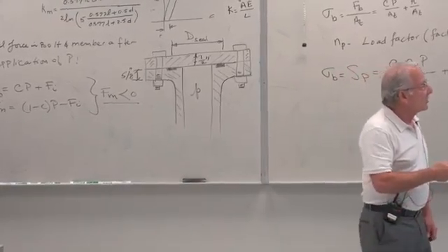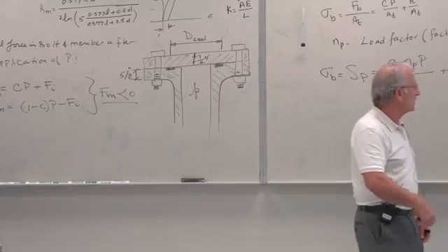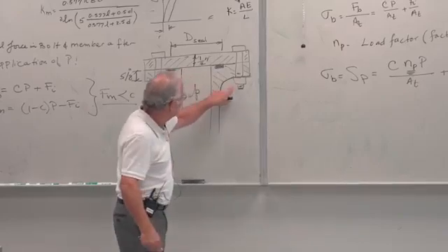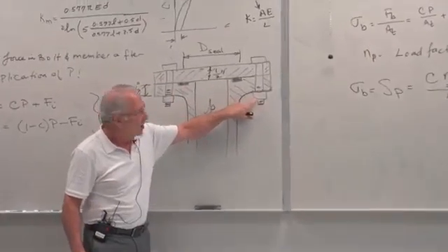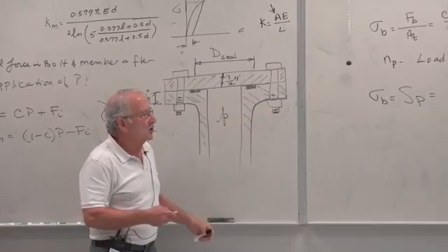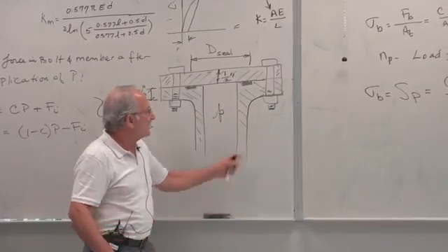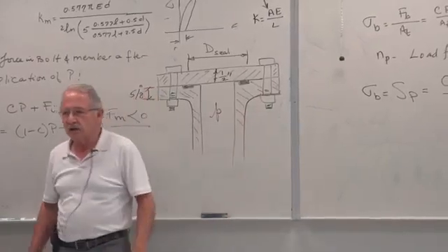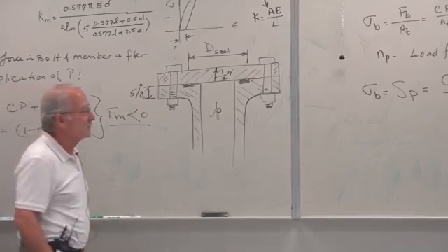Therefore, the bolt length must be larger than 1.125 plus 7/16. That brings the bolt right up to here, right up to there. But of course, you don't find that in the table, so you use 1.75. So you've already got your two threads that are supposed to be protruding, so no reason to add that.